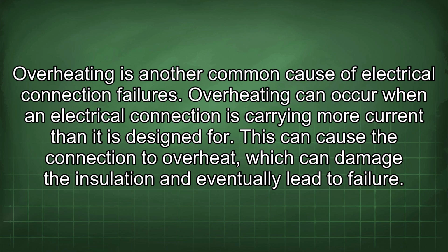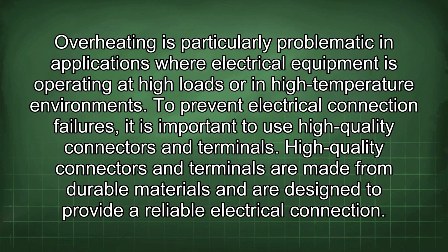Overheating is another common cause of electrical connection failures. Overheating can occur when an electrical connection is carrying more current than it is designed for. This can cause the connection to overheat, which can damage the insulation and eventually lead to failure. Overheating is particularly problematic in applications where electrical equipment is operating at high loads or in high-temperature environments.